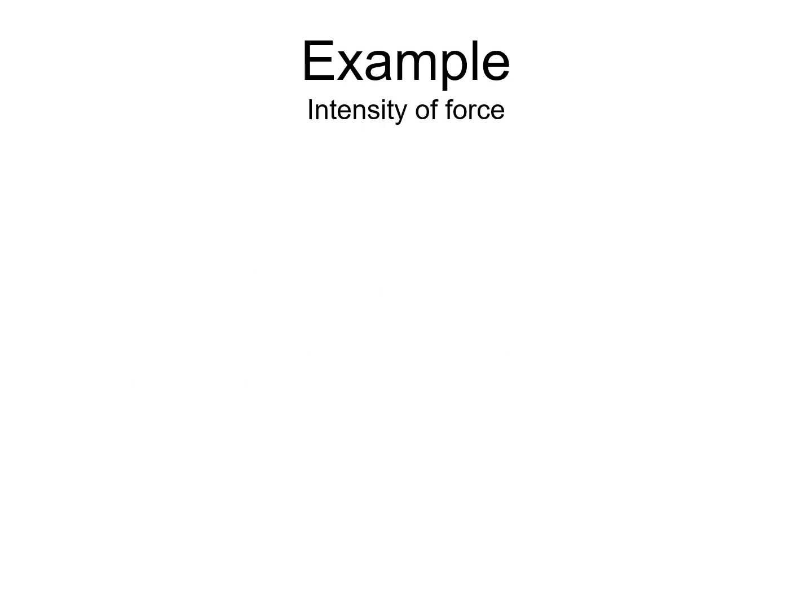Next, we like to look at intensity of force. The unit of intensity of force is pound every inch, or Newton every meter, or a kilopound every feet, or kilopound every inch, or Newton per centimeter, or Newton per millimeter, or kilonewton per meter. So this is intensity of force. Let's say we have this 250 pound every inch. I want you to convert this into Newton every meter.